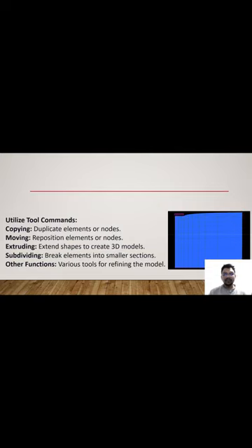As you can see, we have to develop a mesh like this where we have to apply loads on the strip of the footing which we have chosen, and where we have to utilize the tool commands like copying, moving, extruding, subdividing, and other functions where we have to extend shapes and break elements to create the 3D model.